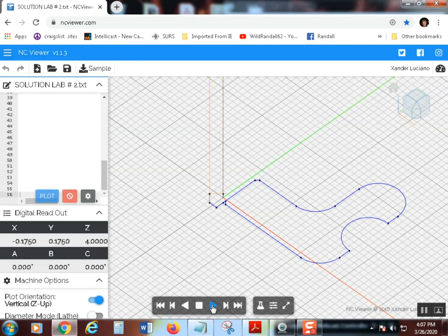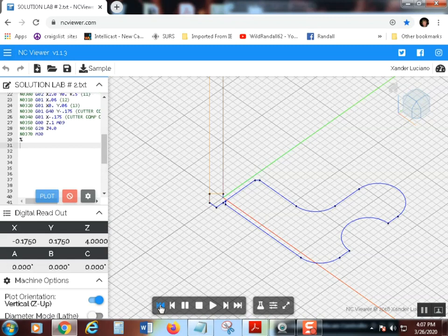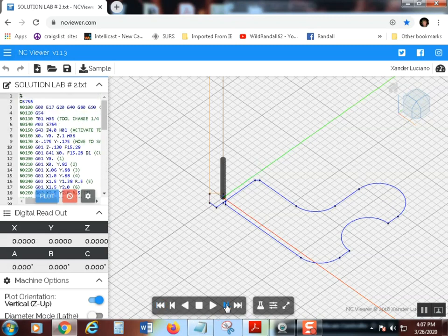Boom. Now, I did that all at once. Didn't mean to do that. I'll start over. Sorry. I'm not going to start this recording over every time I make a mistake. So let's get going back down to all that. Now we're at our safe start spot. Z is coming down 130 thousandths. That gets us 5 thousandths greater than the thickness of the part.